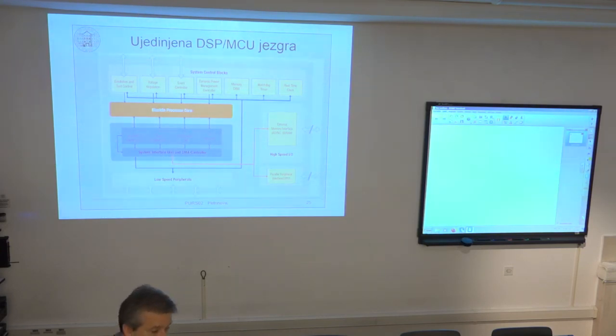You address the first address in the external memory and just say, give me sequential addresses. Okay, give me next value, give me next value. And this can be done practically at the same speed as this cache memory. So the read from memory in blocks is always more efficient than read of individual locations from random addresses.